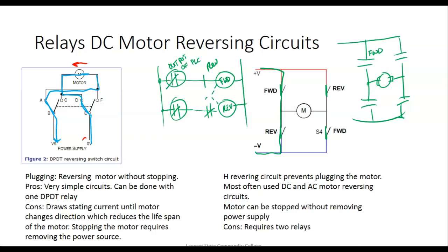So this is kind of the control. It's a little different, but this is the kind of control. If you got that ceiling fan, this is the kind of control you have. So you got a switch that you go between forward and reverse. You got that thing running third speed forward, and you click it down to reverse. You hear that motor humming at you because it's trying to reverse, right? You understand? And it pulls a lot of current. We call that plugging a motor.